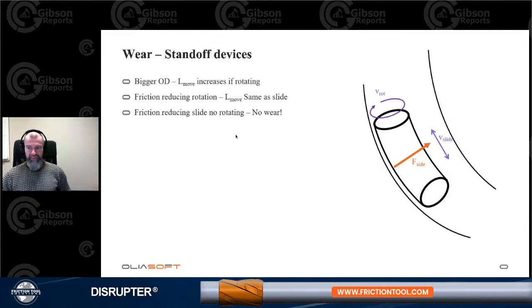And so we might, of course, also have standoff devices added to our drill string, or maybe we're running a liner, for instance. In most cases, you perhaps wouldn't do this if you were running a casing, because that would basically be the last operation that you would see on that casing, as it would be covered by a new casing after the new casing is installed.